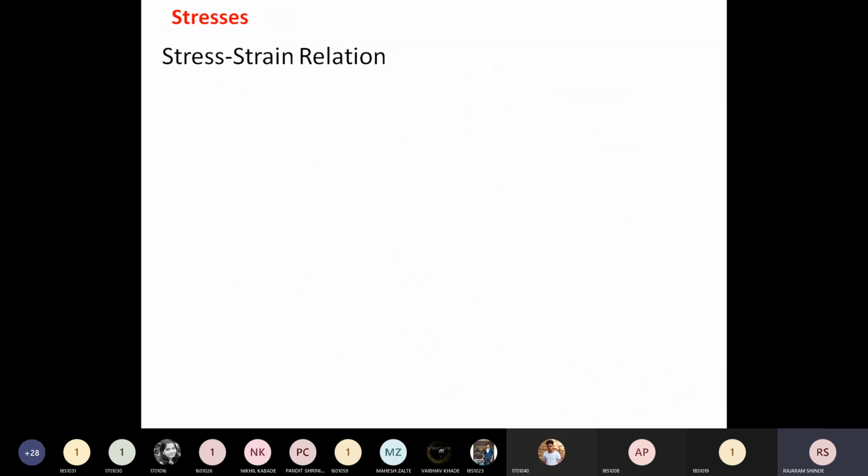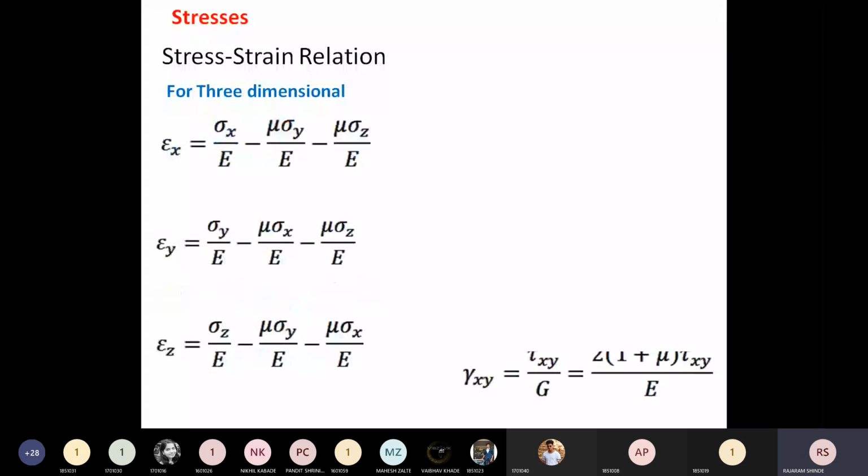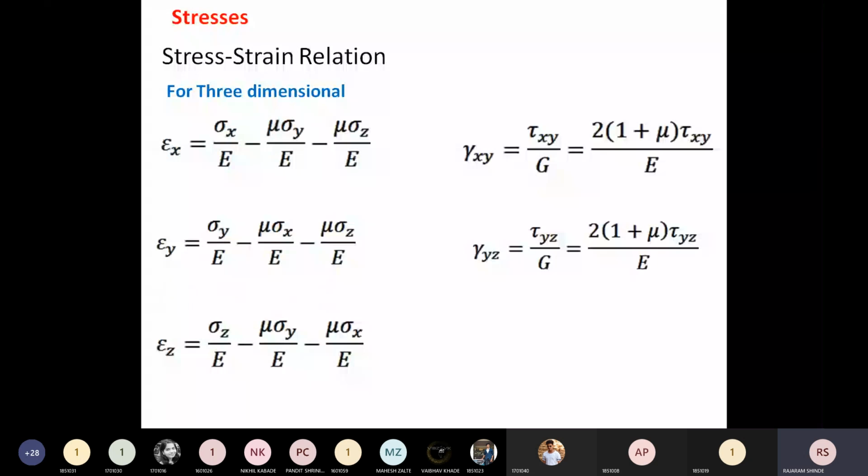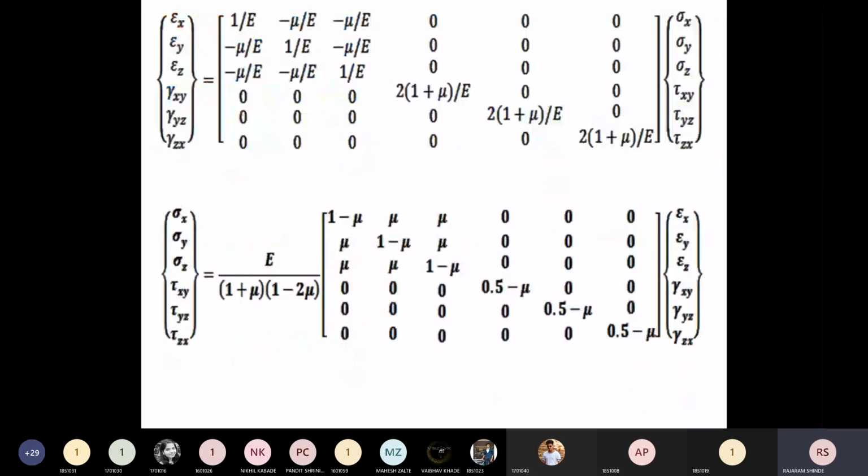After that, stress. Now relation between stress and strain we have seen here. First, in finite element method, first we are calculating displacement, then from displacement we are calculating the strain, and from strain we are calculating the stresses by using this equation: sigma is equal to D into epsilon. Here sigma is the stress matrix, and depending upon the discipline or type of the problem, your sigma matrix will be changed. That D matrix, it is a constant matrix, it is a material property matrix, this also changes. And epsilon is strain matrix, it is also discipline dependent.